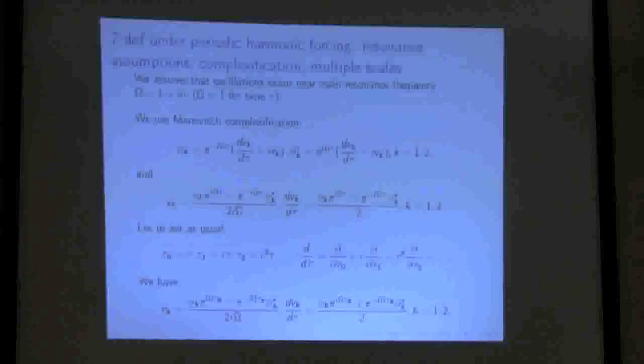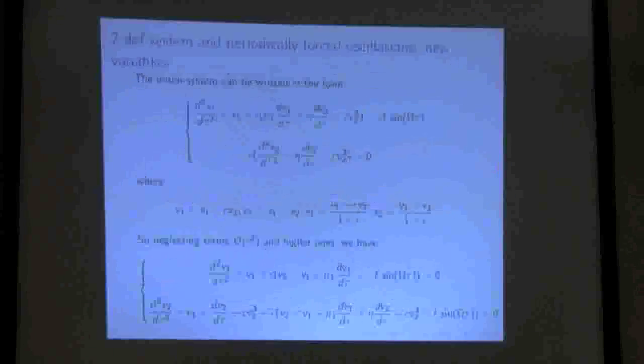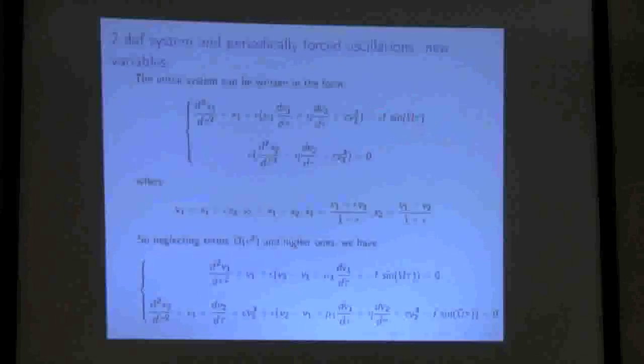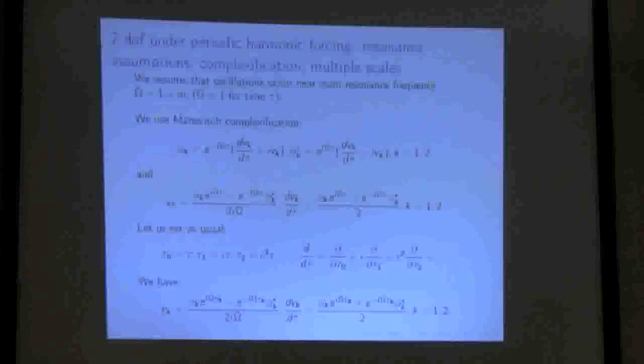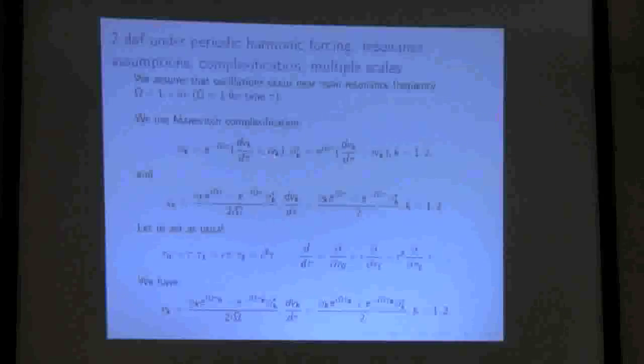Again, I introduce complex variables, but since it is clear, it is as usual, since you have external forcing at frequency capital omega, I introduce phi k, phi k exponential i omega tau is equal to dvk, velocity of vk, plus i vk. So it means phi k in some sense is the amplitude of the complex variable I built here, but it is in some sense the amplitude of the oscillation of the system forced by f sine capital omega tau.